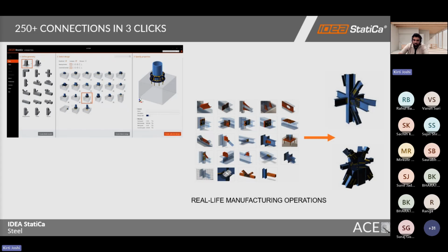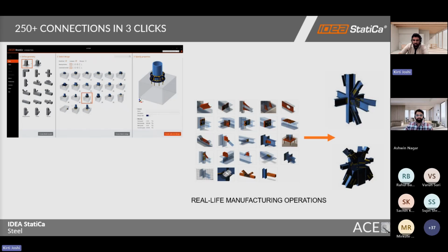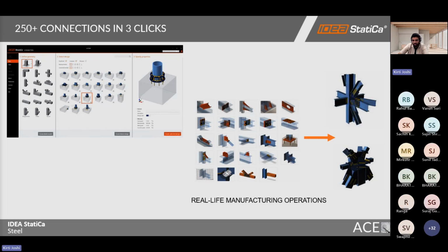So, for example, in the industrial buildings or the truss structure, different members may meet at one node that makes the connection behavior complex. So in such a case, the stresses are not distributed evenly, and as per our traditional hand calculations, this often simplifies the effect. So basically, the software helps to model this connection in 3D, and also allows us to see how the forces flow through the plates, the bolts, and the welds.